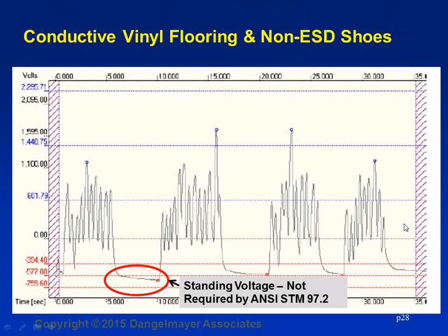In the document, there are several resistance to ground measurements where everything has to be less than 1 × 10⁹ resistance to ground. That is not a surface resistance test. A surface resistance test is either point-to-point or with the concentric circles, and that is actually at the heart of one of the issues that we're concerned about. We'll talk a little bit more about that going forward here.